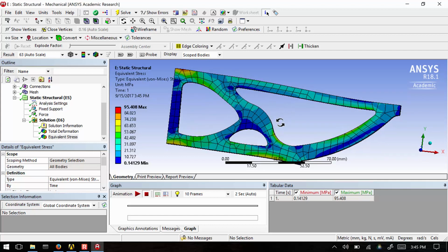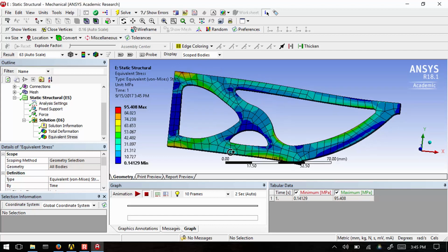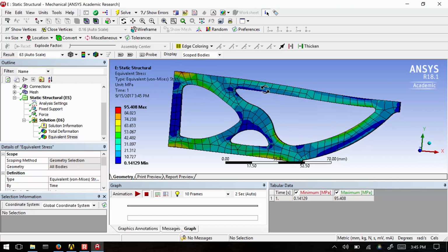Here I'm getting a slightly different geometry where you can see that all the geometry is a little smoother in this one. It's kind of a more organic shape. Because before I was maximizing stiffness while reducing mass, which doesn't really care about sharp corners and things. Here I was trying to have a stress below a certain level, which forces it to have smoother geometry to have less stress concentration. So you can get different results depending on how you set it up, which kind of makes sense.